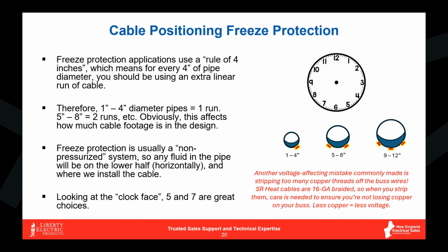So again, if you look at the graphics over here on the right-hand side, I try to relate it to a clock face. Generally, if I'm out on your job site, you're probably going to hear me say 5 o'clock, 7 o'clock, as far as where to put the cable on the pipe. Generally, we don't put it flat on the bottom. That was a practice that we got away from about 20, 25 years ago. The reason being, it's really not that consequential now, but in some of these process applications where you would have pipes prone to leakage, gravity is going to pull that moisture to the lowest point on the pipe, which is 6 o'clock.